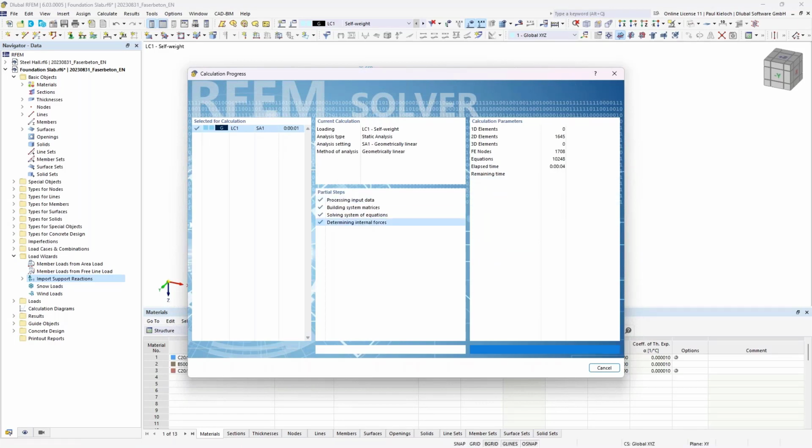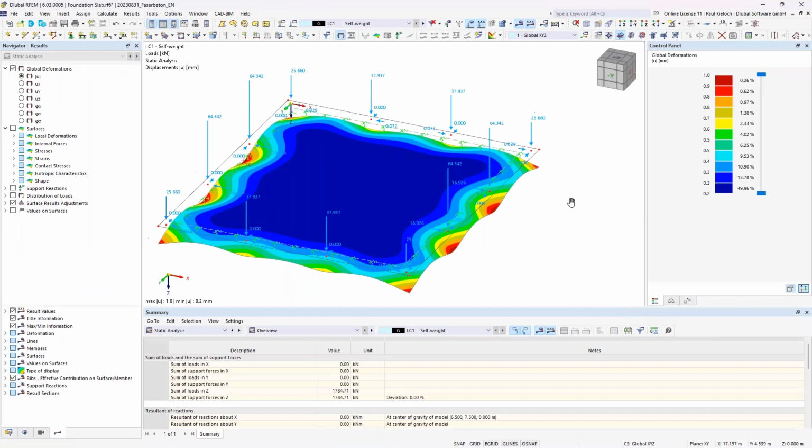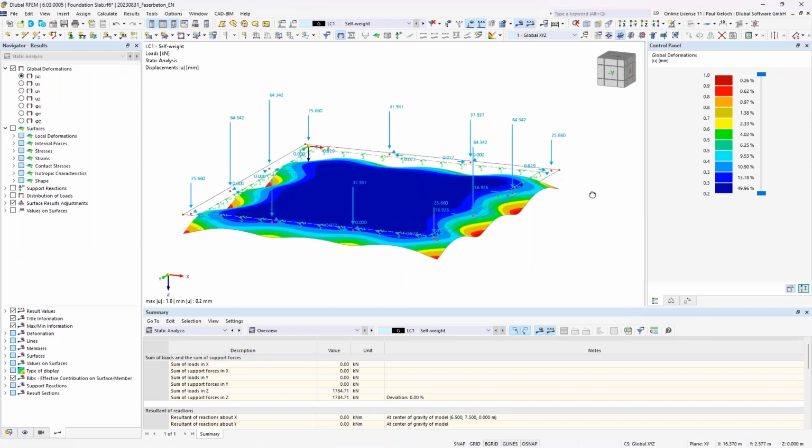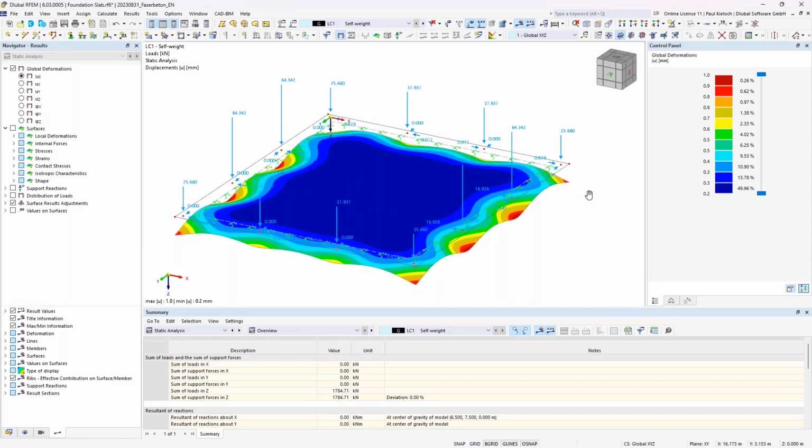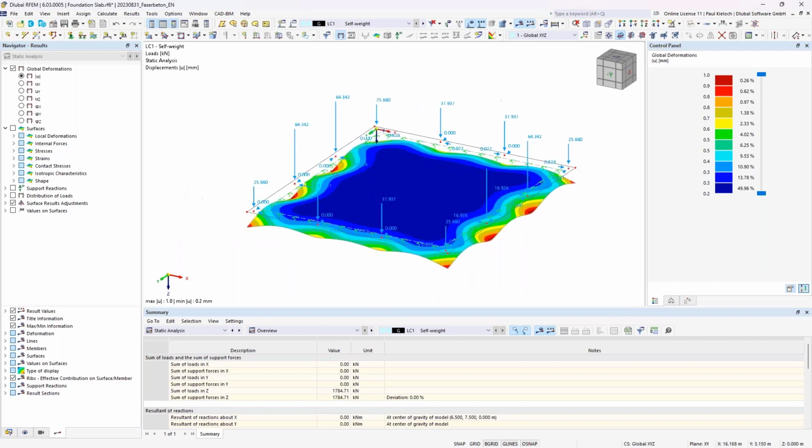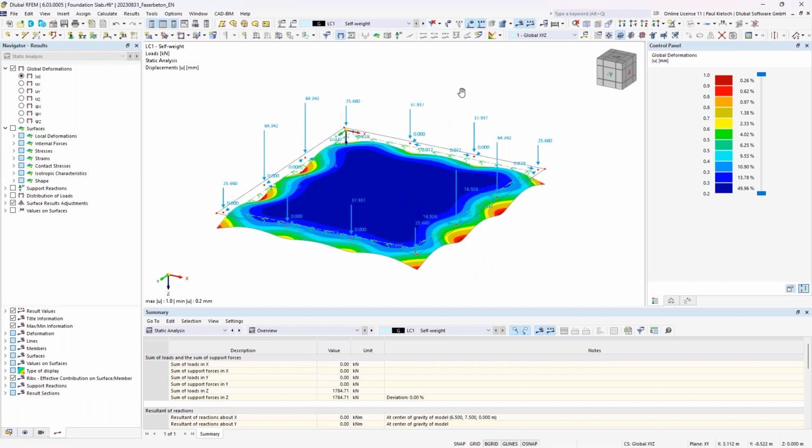So both files are now combined together. So if I would update anything on the loading of the steel hull, the program would automatically update here this loading. That's also new compared to RFEM 5. In RFEM 5, this was a free nodal load.